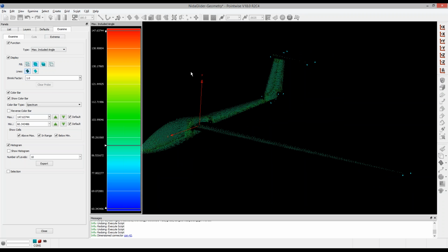That's one of the reasons why I set my maximum included angle for a quad to be 150 degrees, because if it violates that, it'll split it into 2 triangles. So what are some cases where you might exceed 150 degrees? Well, if the topology of the geometry means that the mesh that you create on that surface is going to have an included angle greater than 150 degrees, that's one area. There are a few ways to fix that actually.